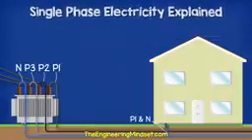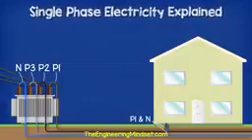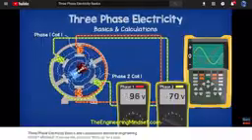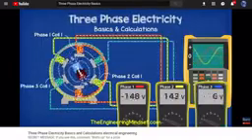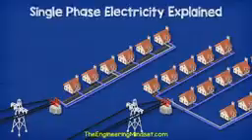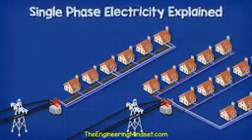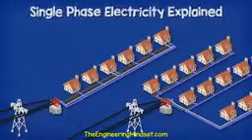The electricity is distributed in 3 phases, but in this case we're looking at a single-phase installation, which means the property is connected to just one of these 3 phases as well as the neutral. We've also covered how 3-phase electricity works in a previous video, do check that out, links in the video description below. Now, each house in a street might be alternately connected to a different phase, or different streets might be connected to different phases. This is just to try and balance the demand on the transformer.